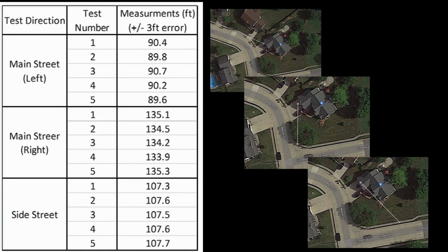Here's how we tested GarageAuto. The main metric we tested for was the connection range for the Bluetooth. This is because the two major metrics involved with the functioning system were not distance sensitive, in the case of the geofence, or had virtually 100% success rate, in the case of successfully opening the garage door when all other criteria were met. The results of the range test can be seen in the table below. Our error came from two main sources: the tool we used to measure and the fact that we cannot move through walls to get the ideal point A to B distance.